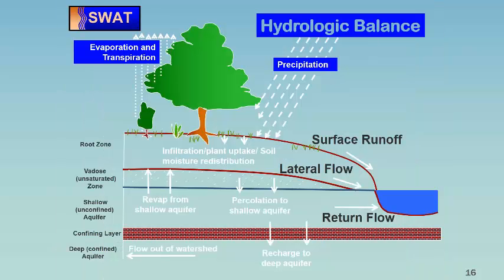So this one figure shows you in a nutshell what hydrological balance SWAT actually simulates. You take an HRU that could be represented by a tree crop, or a grassland, or a cropland, or a range or city or whatever it may be, and you have rainfall that is going on a soil. That soil could be divided into up to 10 soil layers called the root zone, and then you have an unsaturated or vadose zone that follows,